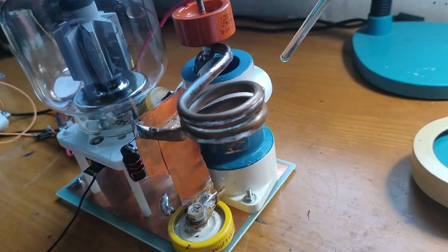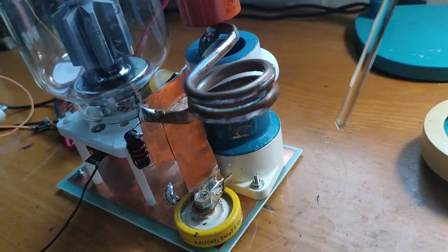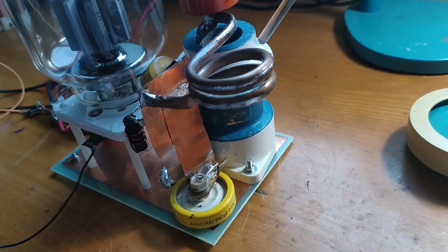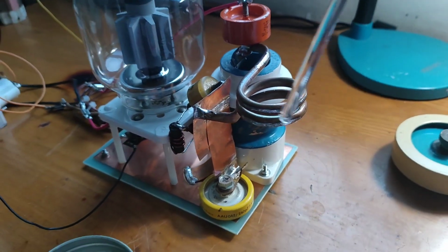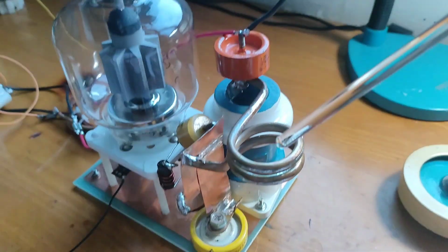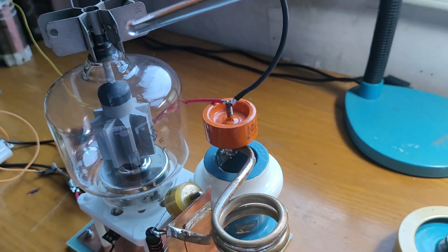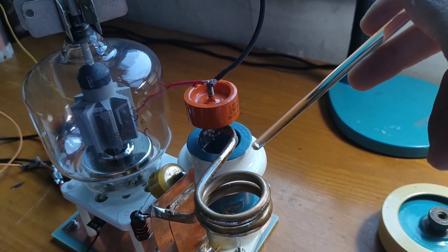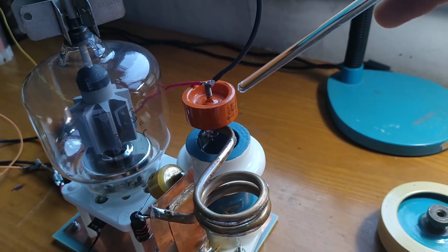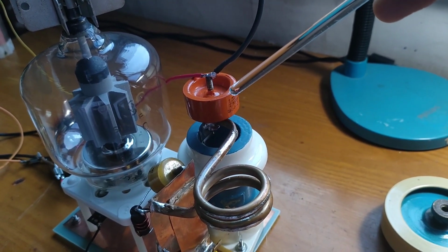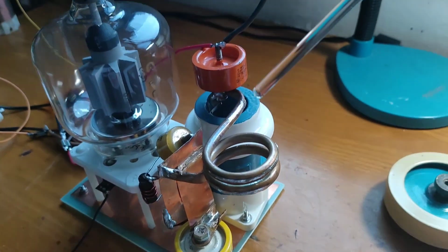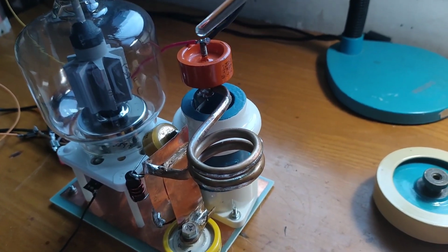And the importance of the capacitors in the resonant tank, I think I do not need to talk about that. You all know that. And also the DC blocking capacitor here, from the anode to the resonant tank, also needs to withstand a high reactive power. And I recommend ceramic silver plated capacitors as well.